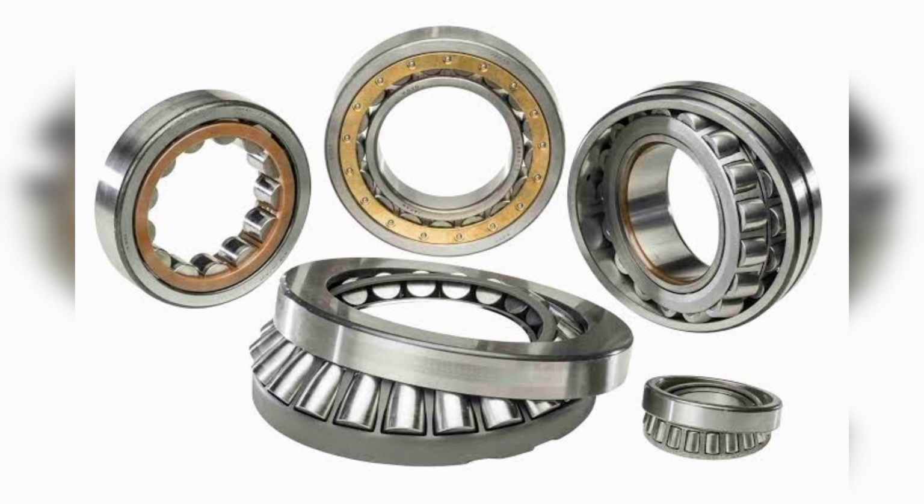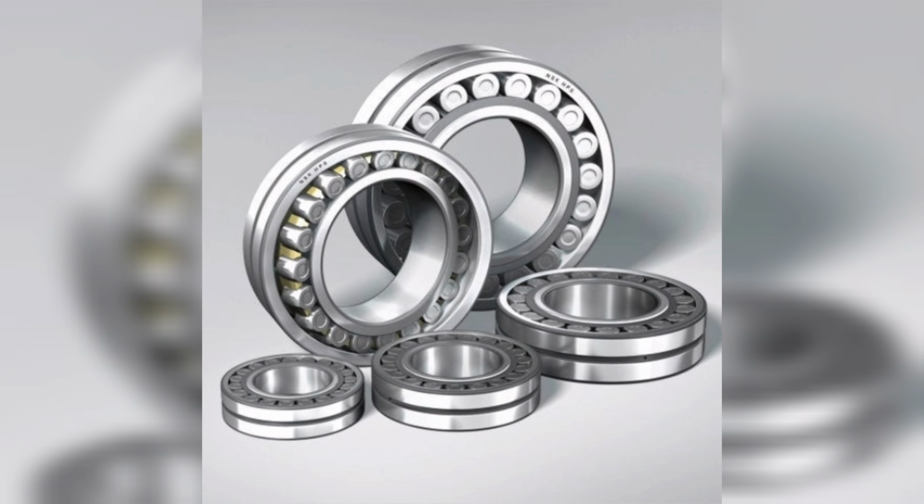Roller bearings. Roller bearings are characterized by a line contact. This type of contact means that roller bearings have a higher load rating than ball bearings of the same size. However, the speed ability is lower than a ball bearing due to the increased friction of a contact line.